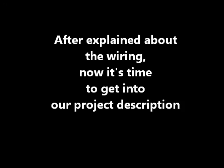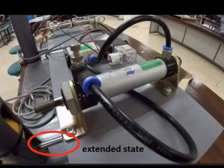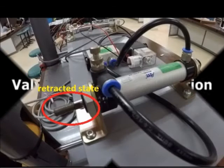Starting from here, Aaron will explain to you all the operation flow using the ladder diagram. Before all else, we should clarify the original state of all 4 cylinders. So for the bottom valves, the original state is in an extended state. But for the top 2 valves, the original state is in a retracted state. So when the top valves are activated, they extend, and when the bottom valves are activated, they retract.